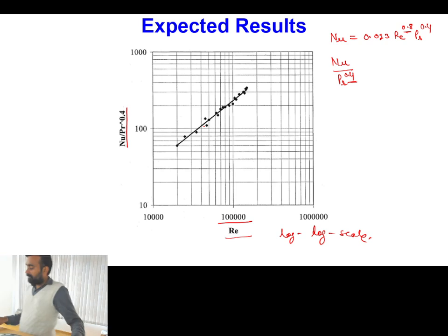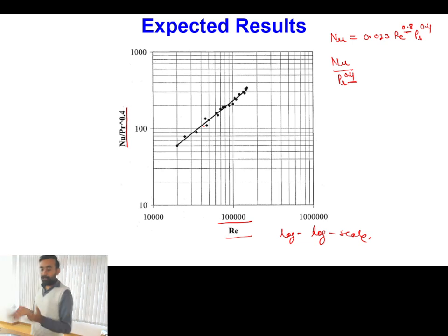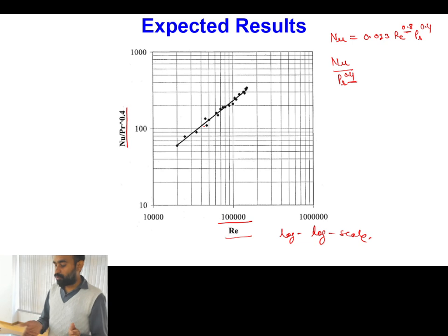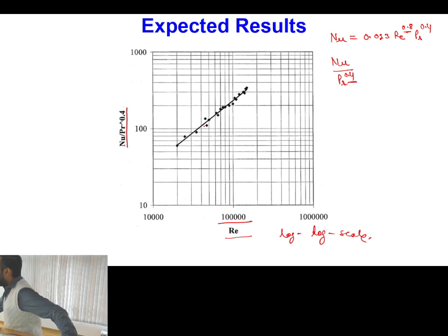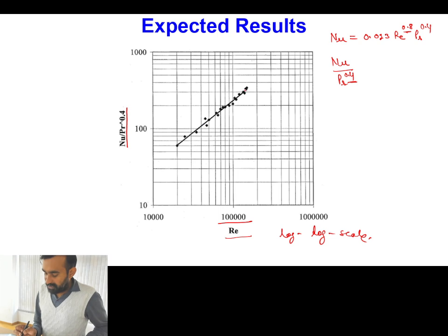So it means that now by just performing the experiment for 12 mm diameter pipe, if we are able to establish that this particular equation is satisfied, then I need not repeat the experiment for 2 mm and 35 mm diameter. What I can do, if I have to define heat transfer coefficient for any turbulent flow situation, I can use the Dittus-Boelter equation.